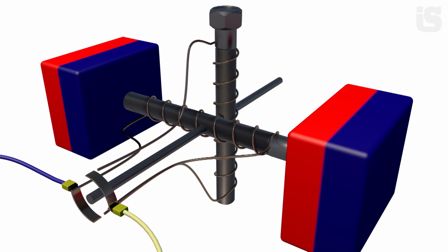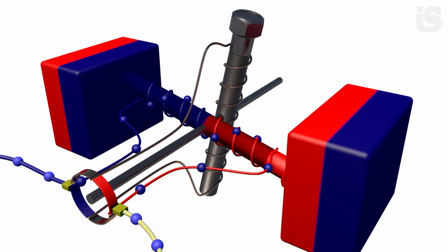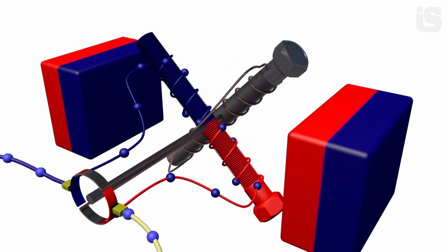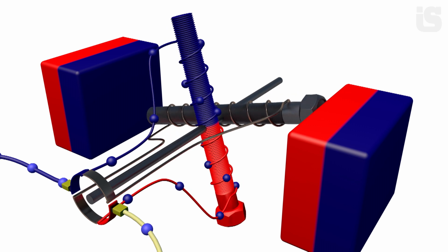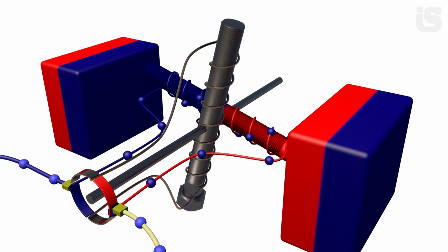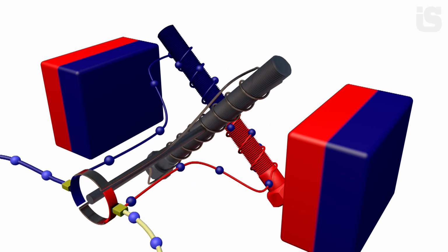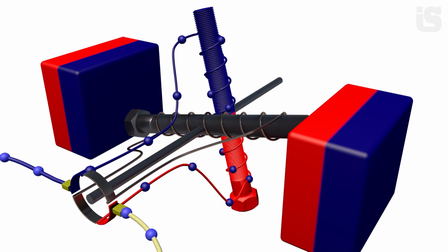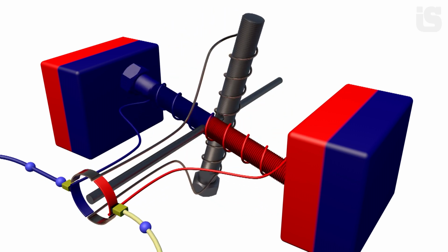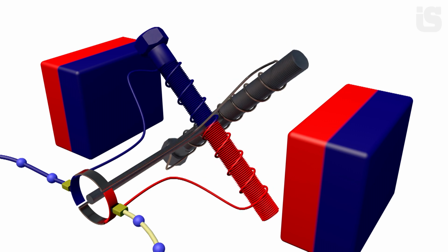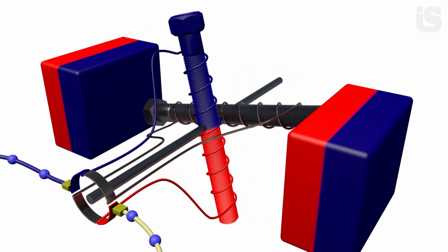Let's add another identical electromagnet with commutator segments to the design. Now, when both magnets rotate, the electric current will change direction as the commutator segments come into contact with different brushes. Accordingly, the poles of the electromagnet will also change places. Let's close the circuit and turn on the electric current. In this design, the rotation will be stable.